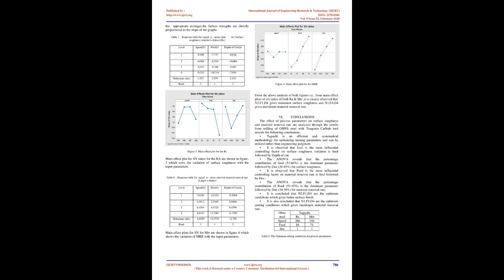The results of ANOVA for the response material removal rate, MRR, are shown in the following tables. 6. Material removal rate, MRR, versus speed, S, feed, F, and depth of cut, D, is also allowed to determine the effect of any two cutting parameters, whereas the other parameter is maintained constant throughout the design of experiments.